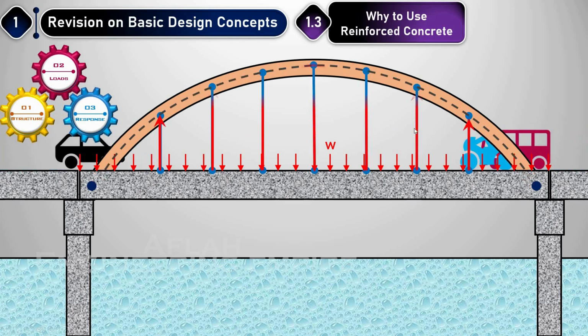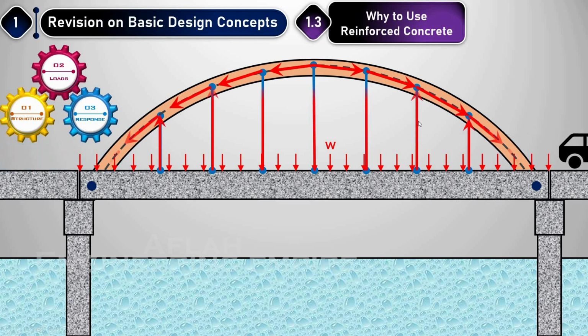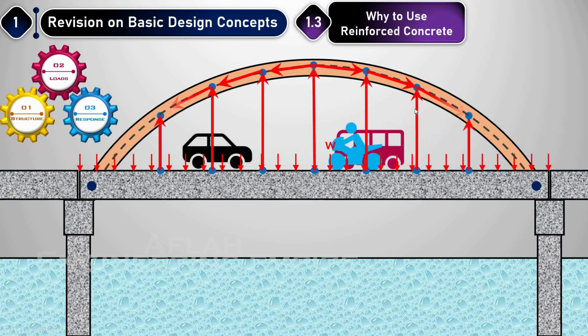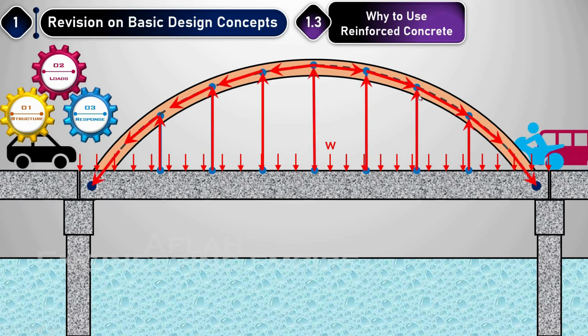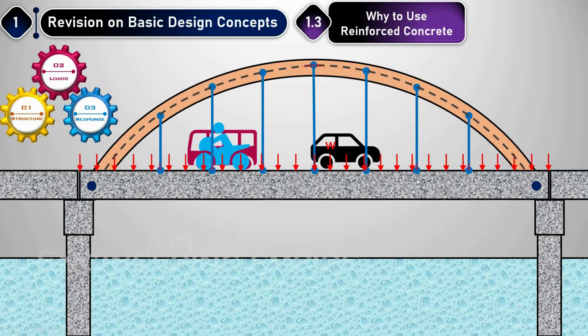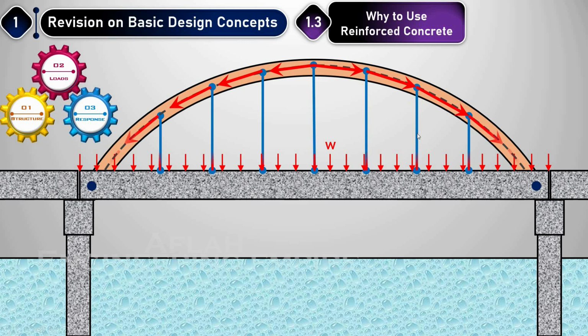So we surely need to provide a material that is strong in tension. You may need to provide tension cables, or high yield strength cables. As an engineer, I may not provide concrete here, because concrete is weak in tension. You need to provide tensile resisting cables. So this is how you will design it.